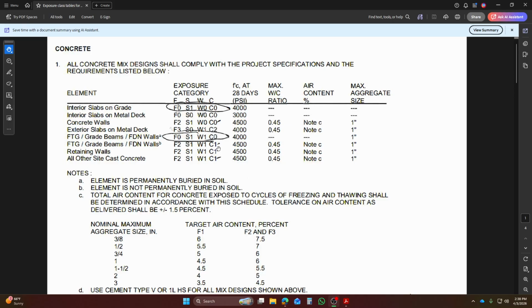So the mix design, being simplified, we don't create a new mix for everything. If you notice, Suncor, Western Rock, when you're testing, have a lot of the same mix codes, and you see them on plenty of different jobs. When they go and bid on these projects, they go through this set of plans and they have their mixes that they know meet those requirements. And then once they do that, they submit their mix designs that are going to meet the requirements that the plans are specifying here.